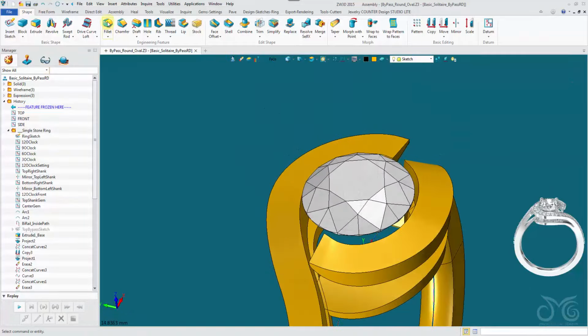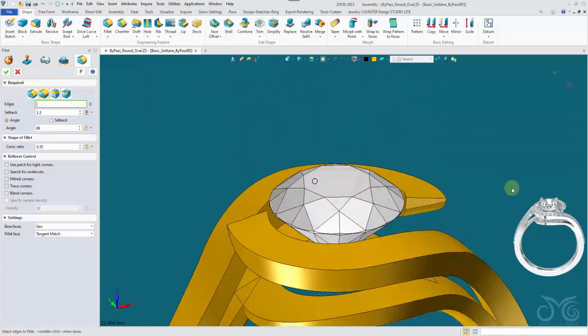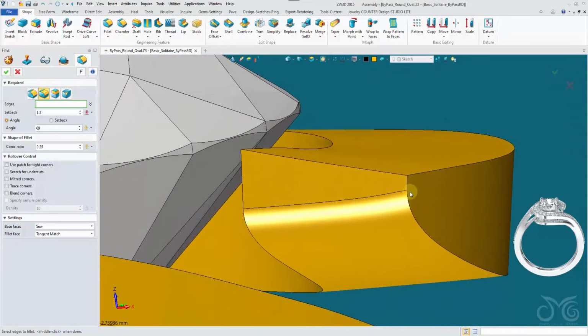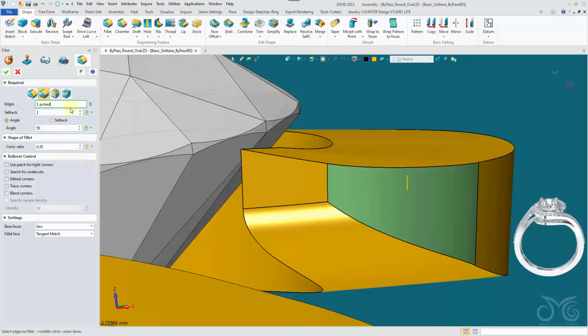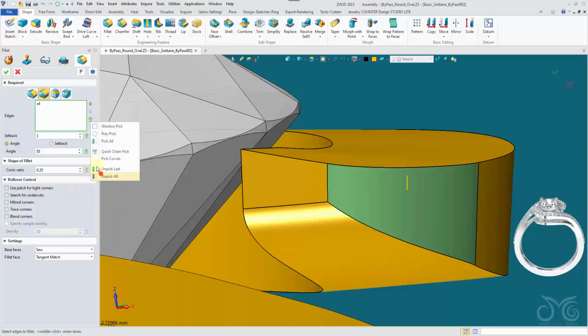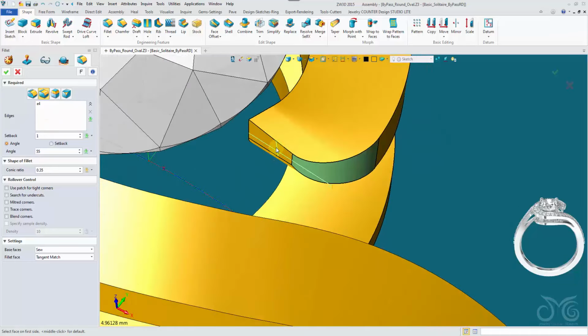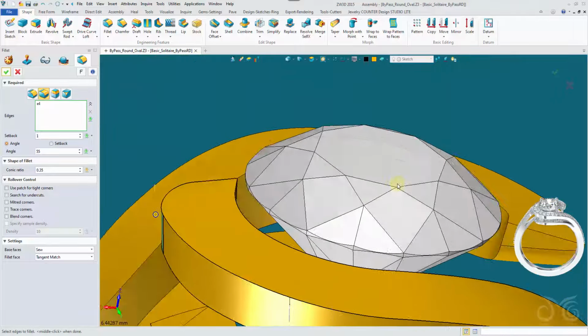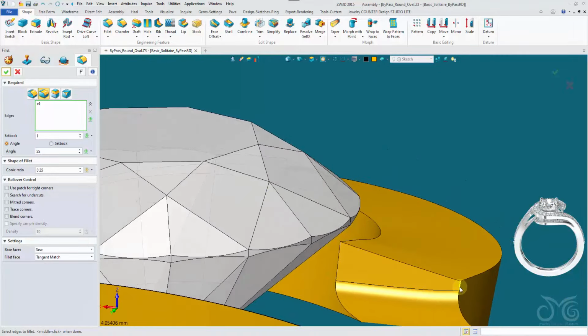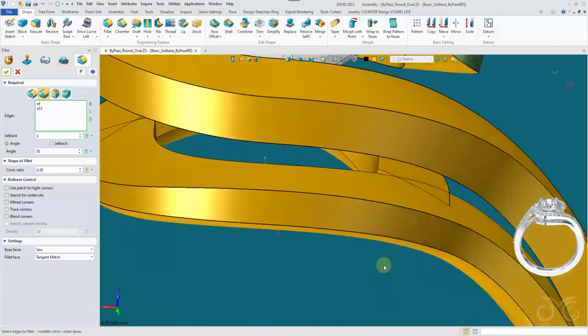We'll come in with another fillet, elliptical again. This time we're grabbing this small edge. Okay, can't cope with such a large initial fillet. Let me unpick and grab again to make sure we have it right. Pick that face, pick the edge in the face again. We'll do the lower portions at the same time.